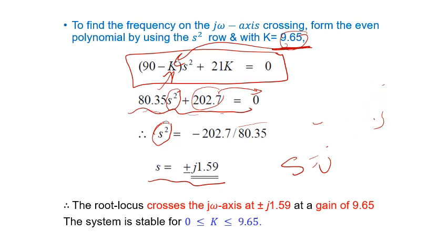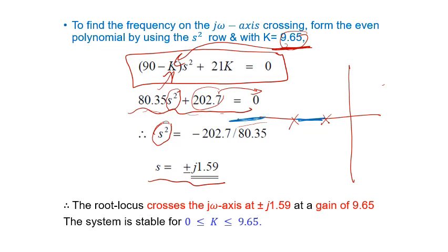if I want to show it on the S plane, this is the S plane here. We said that as the poles move, they are going to move to a certain point. Remember that there is a line here, but I'm not showing it. They are going to split at the breakaway point, and they are going to cross the j omega.